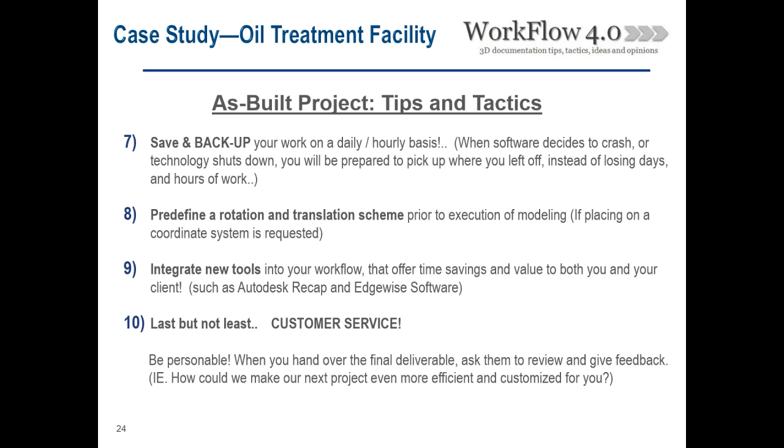Good question. It is targetless, but ReCap does have a way, similar to other software, where you can go in and add your own. You can click on your own points and make them control points to use from scan to scan to help improve the accuracy, which ties into another question I saw.